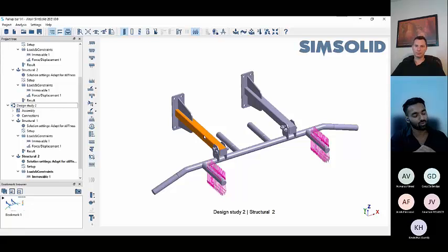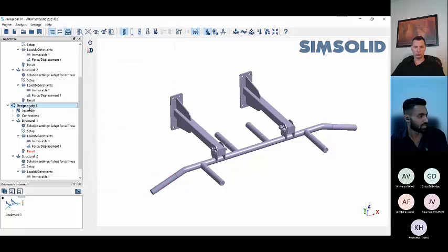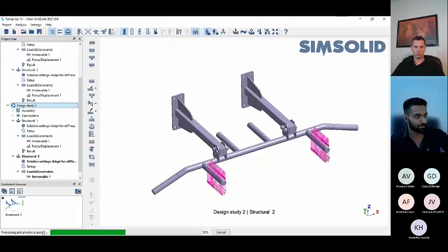And as we go to the solution passes, there are 3 passes as you might have seen over here. I'll just change a bit so that we will be able to see again. So if I just solve it over here, you can see there are 3 passes. In each pass, the solver tries to calculate the error. What is the error coming in a body? And if there is some error, it tries to enrich that very body or domain with more equations and more degrees of freedom, so that our solution is quite accurate.